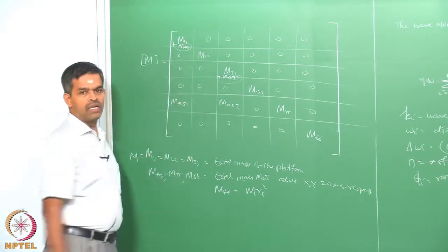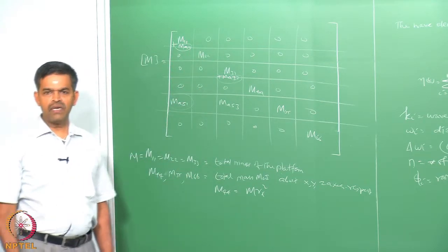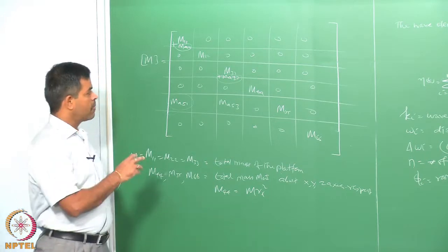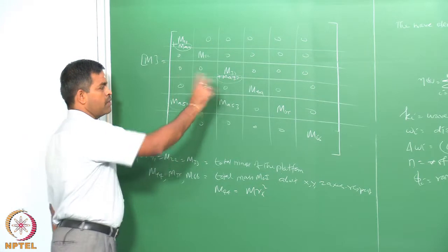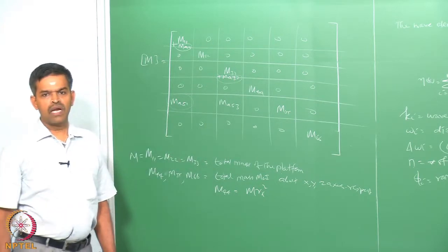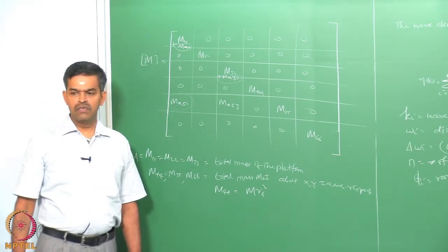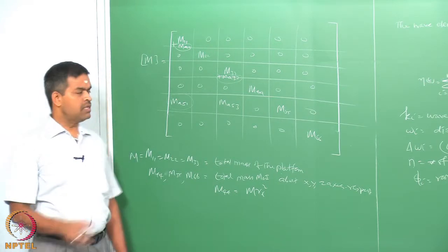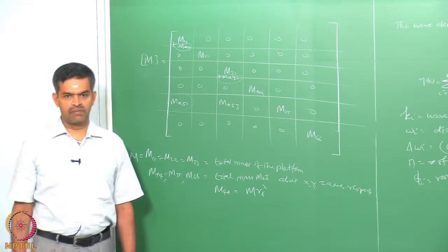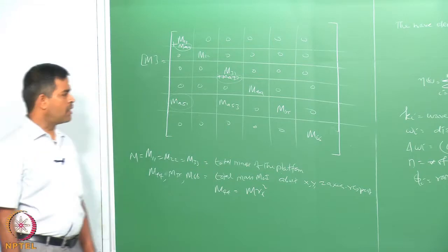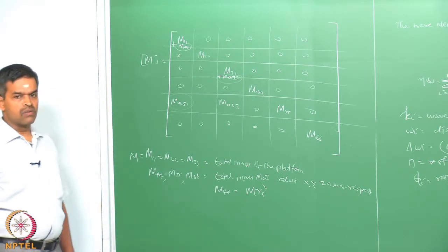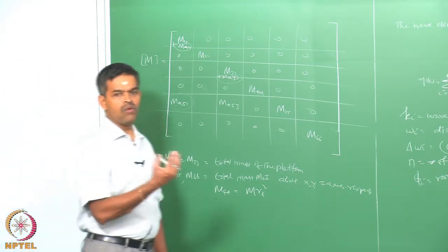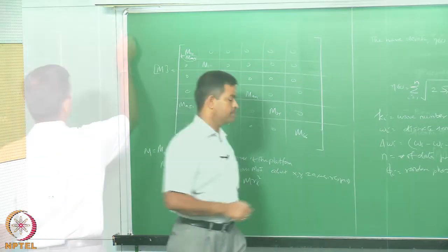Ma11 and Ma33 are the added mass terms in the surge and heave degrees of freedom, whereas Ma phi 1 and Ma phi 3 are the added mass moment of inertia due to the additional mass in surge and heave degrees of freedom respectively. The heave added mass on the TLP hull is taken equivalent to the mass of the hemispherical volume of water.